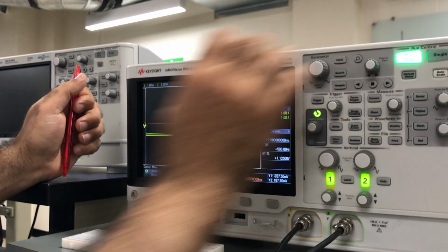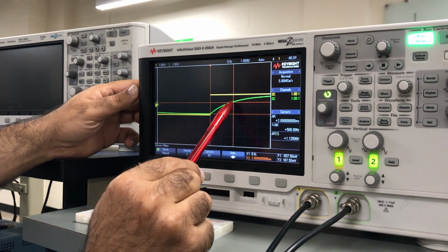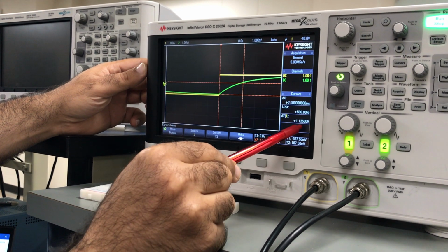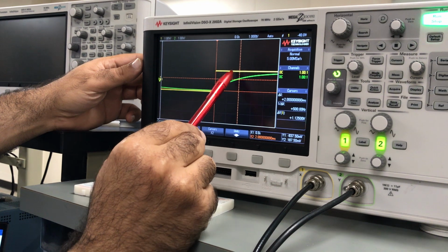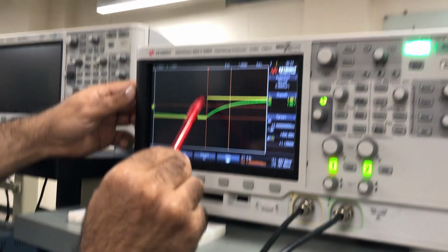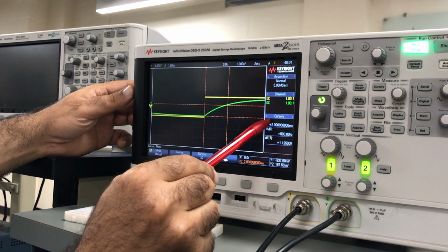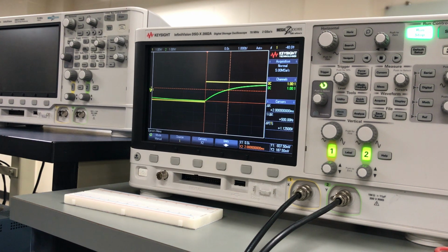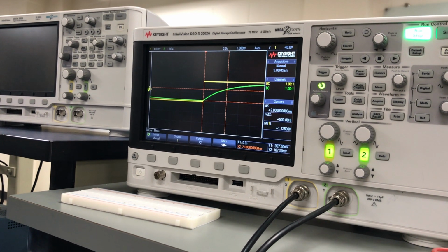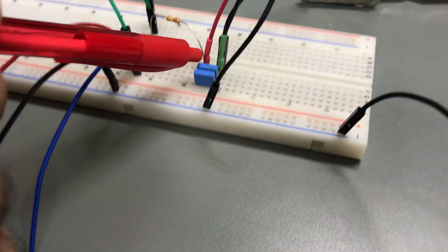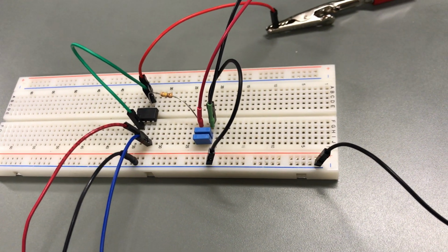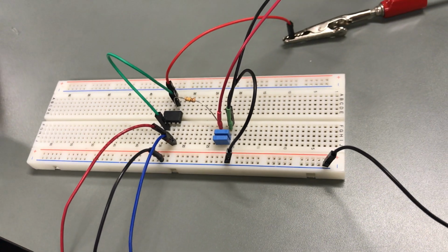If I try to make it bigger, here, this is the curve. So I used this height, which is 1.125, which is 63.2% of the big value. And I found that the time constant for the next case is equal to 2 milliseconds, which is double the first case because I connected a capacitor in parallel. So the total value of the capacitor will be equal to the summation of both of them. And I know that RC, if I double C, then the time constant will be doubled.